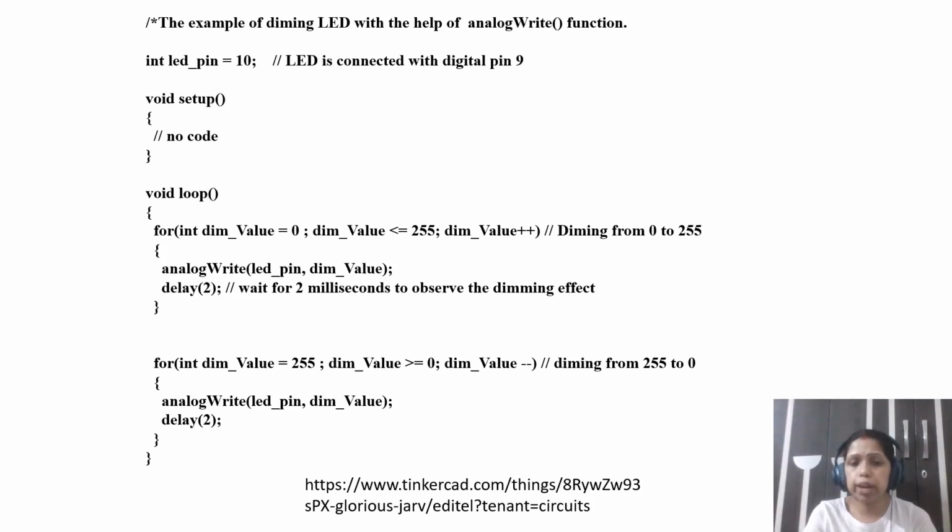So for that, nothing is required under the board setup. But when you come to the Arduino, if you write the Arduino IDE code, you have to write Serial.begin and the Wi-Fi details into the setup function. This I will discuss in a coming lecture.